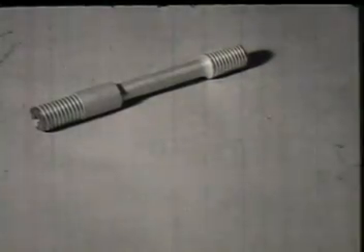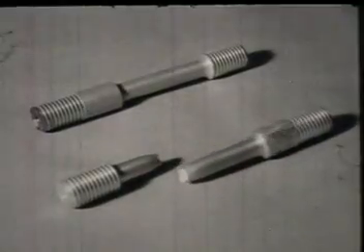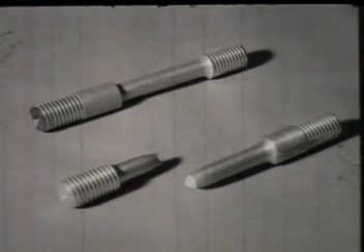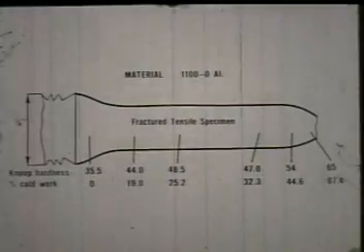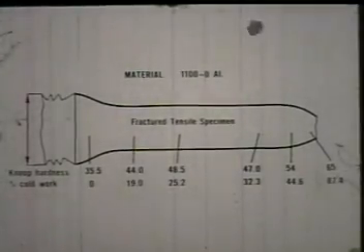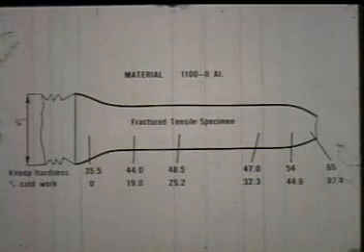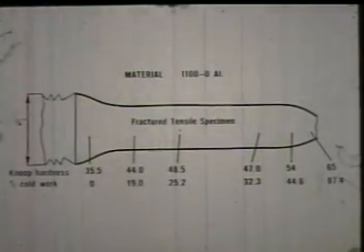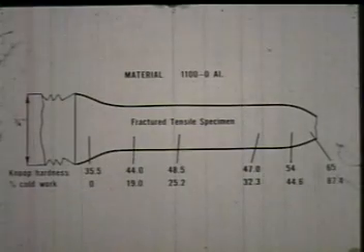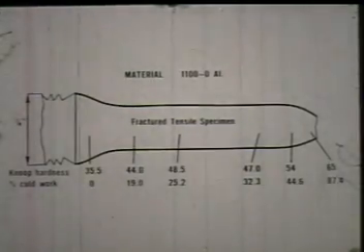To obtain an appreciation of how much work hardening is represented by these Knoop values, a similar study was made on a tensile specimen after it was loaded to failure. A longitudinal cross-section of 1/2 of a fractured tensile specimen of annealed aluminum is illustrated. The average Knoop hardness at the threaded end of the specimen, where no plastic deformation occurred, is 35.